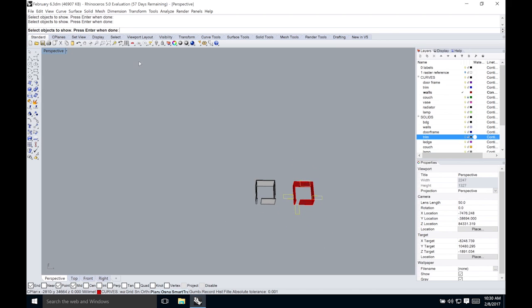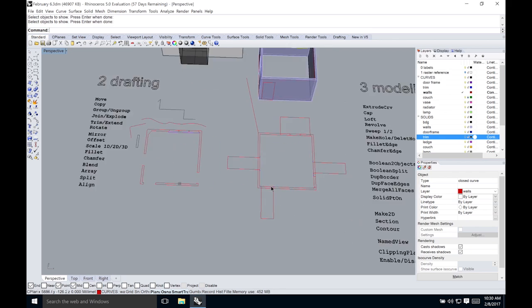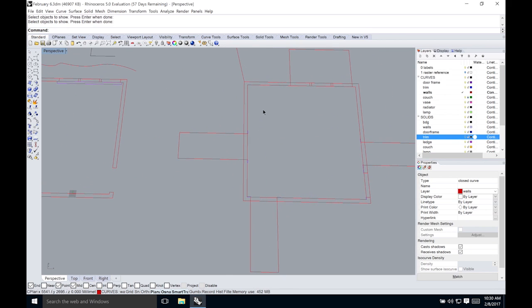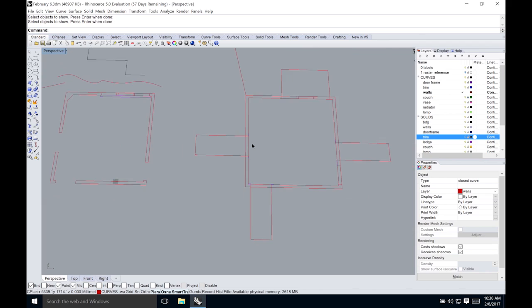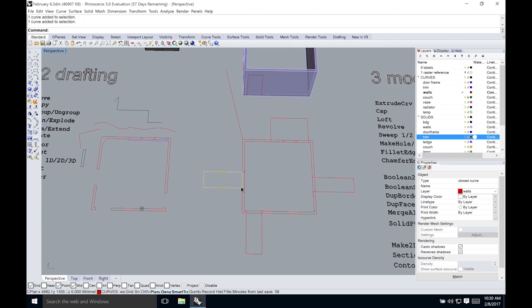So what I just did, I clicked on show selected objects here under the sub options of the hide and show tab, and so right now Rhino is showing me all the things I have hidden in my model, and I can select whichever I want to show and then press enter, so they came back to view. When I was drafting, after marking where the openings are located, I created these rectangles and I rotated them up to an upward direction.